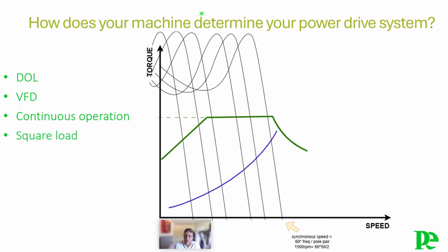Machines that impose a load evolving with the square of the speed are quite common in various industries. Examples include centrifugal pumps, forced draft fans, induced draft fans, sinter fans, boiler feed pumps and centrifuges. The square and linear loads are often referred to as variable torque applications. Variable speed for these machines offers significant potential for energy savings with short payback periods. These applications fall under the category known as general purpose or standard applications.